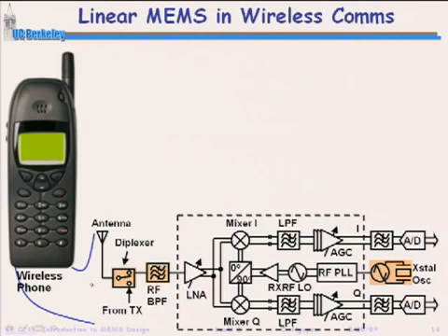Okay, and why that filter is there, it's there to knock out those interfering signals so that you only see the signal you want. Only the signal you want, plus a few other signals that this circuit can handle, are received by this circuit. Because these transistor circuits, they have a limited, what's called a dynamic range. Okay, if you give them too much signal, they won't be able to decipher the small signal you're looking for.